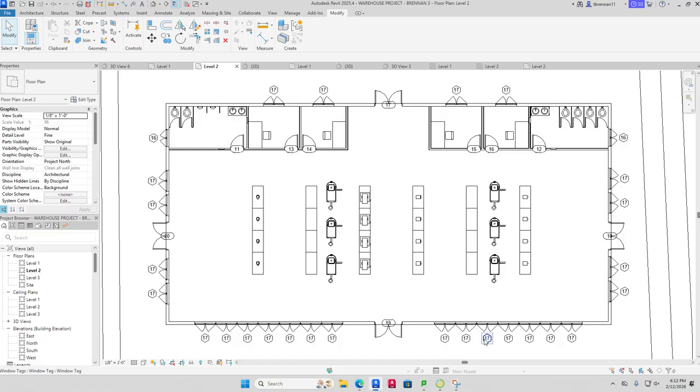Press escape again. Let's try that again. And select all instances. All right, and then just make them all 3. Change the elevation level to 3. And that'll move them all up just like that, all at once. Okay? Okay, thank you. You got it. It's good. Good, you guys.